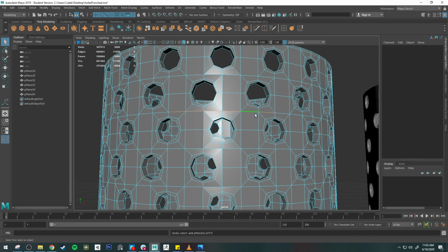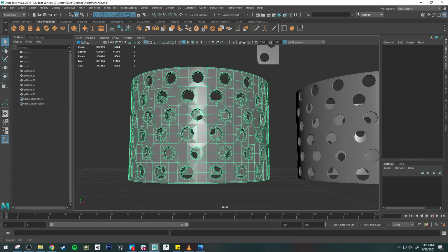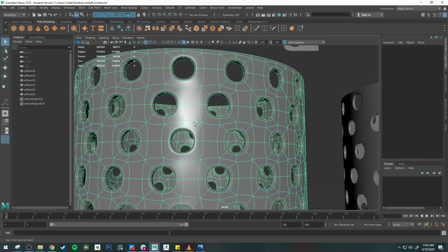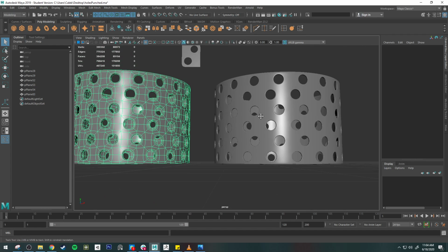And this all has to do with the way your meshes are going to be smoothing with the smooth preview button turned on. That really is affected by how close edges are. If two edges are close to each other and two other edges aren't, then they're going to look different. And then things like poles and other modeling artifacts cause a lot of pooling and distortion, right?